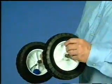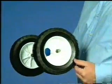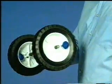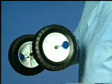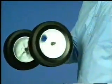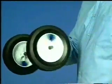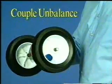Another type of unbalance may actually be statically balanced, so that the rotor will stay in any position when it is at rest, but when it is spinning, it exhibits unbalance. This is because each end of the rotor is unbalanced. The unbalance amount is the same at each end, but in opposite directions, so that the rotor is balanced while it is still. When the rotor is spinning, centrifugal force causes the unbalanced weights to pull on the rotor. In this case, they would pull in exactly opposite directions. This type of unbalance is called couple unbalance.